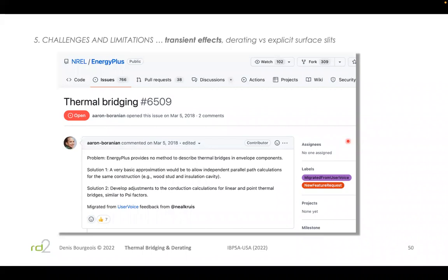And we started discussing a critical point, which has to do with maybe more of Michael Don's question initially. What happens when you have, in milder climates where, maybe it's 2000 heating degree days or 1000 heating degree days, significant thermal mass, or maybe it's an existing 19th century building that doesn't really have a clear insulation layer to derate? How do you factor in thermal bridging without modifying the transient response in a significant way? That's a good point. We recommend not to go down this path, but there's no easy solution out of it,